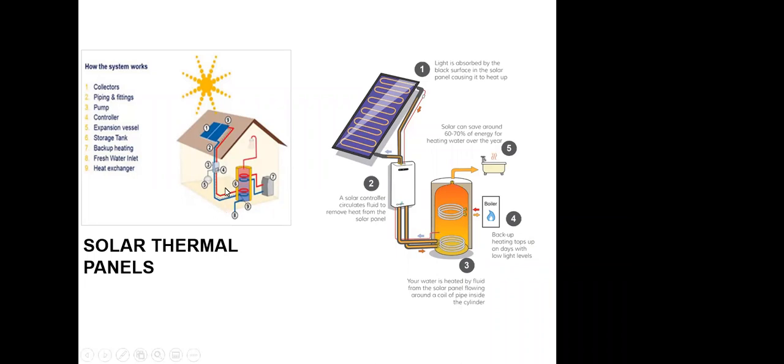Okay, so this looks more reasonable. We have a tank here, we have the solar thermal collectors connected to the tank, and we have the boiler connected to the tank as well. And then this is the hot water supply, whatever. Okay, so we do need a backup heating. So connecting a boiler to the tank. So I wouldn't go 100% solar with solar thermal collectors, because if we don't have sun, we don't have hot water. Okay, so use a backup plan like a boiler.